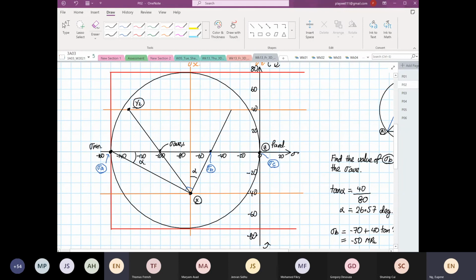So when we have that now, right? So this is the center of our circle. Right? There's the center of a circle. Now we can construct one of the Mohr circles. Okay, we can construct our XY plane circle. So our XY plane circle, it's 50. So I'm going to go up by 50.